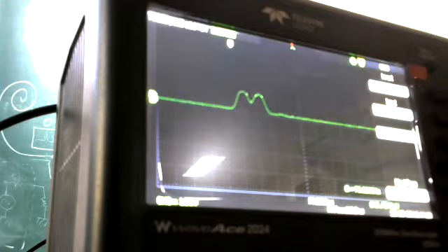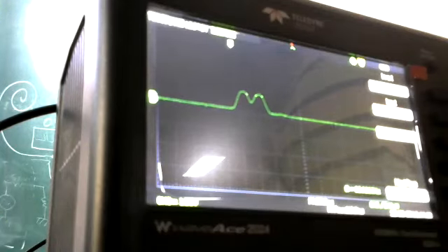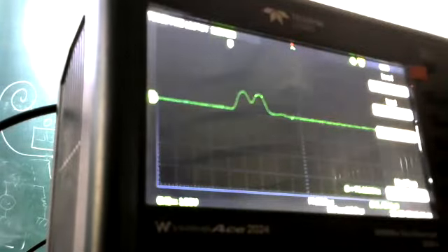What does that tell you? That the time of the pulse rising and falling is longer than the round trip time for the pulse to go and come back. So that's why there is some interference, but again local in time, so it just adds at that particular point. That's why the voltage here is slightly higher. Okay, we can fix this.